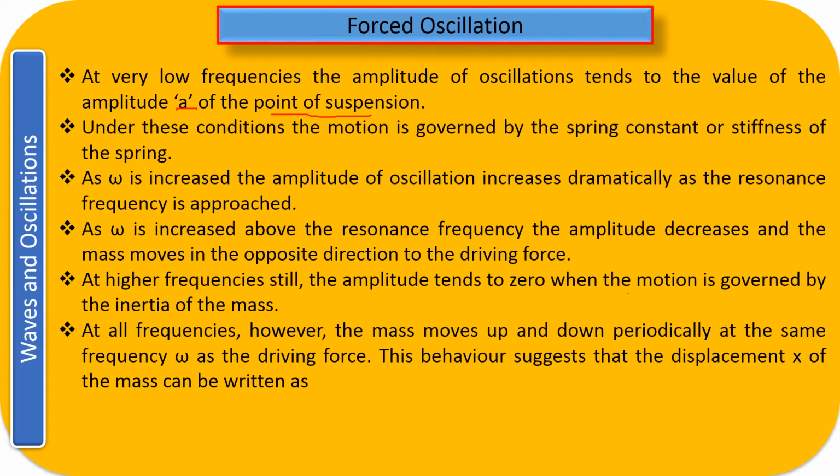So if you are going to increase the angular frequency further, then the amplitude is not going to increase, rather it is going to decrease. At all frequencies, however, the mass moves up and down periodically with the frequency omega. So whatever frequency you have given, the mass is going to oscillate with the same frequency omega. I am not talking about the amplitude, but it is going to make the displacement with the same angular frequency omega.